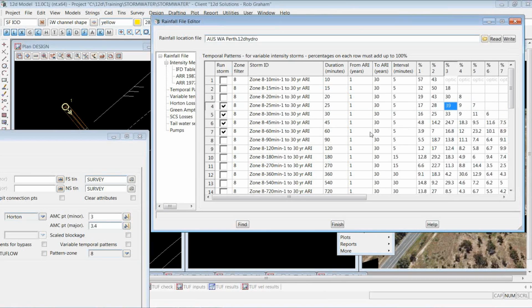Larger catchments, or areas with storage, it may become more dependent on longer storms. So when we go to size our culverts and to check the maximum upstream water levels, we're going to want to run several storms, which is what we've done in this case.